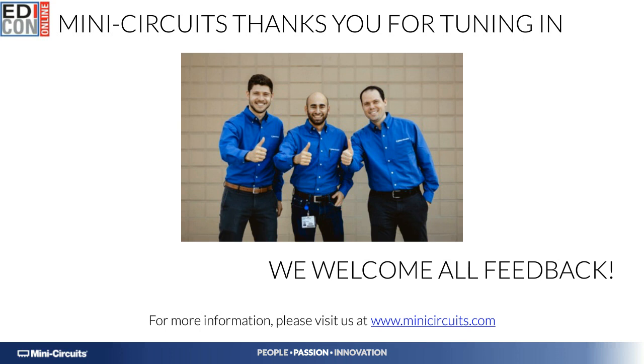Oh, that's a great question. So the short answer is yes. In theory, we could design any filter with any percentage bandwidth within 3% all the way up to comfortably 35-40% bandwidths at those frequencies. The question that we will have to pose afterwards is how much insertion loss can we afford?